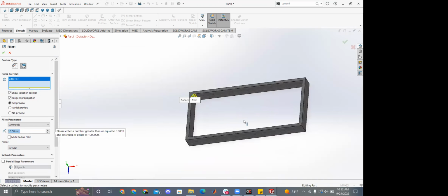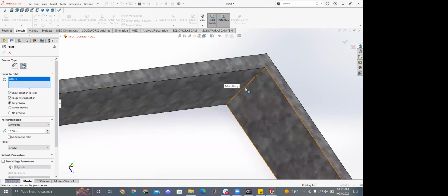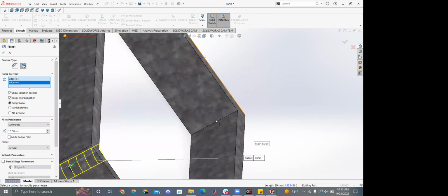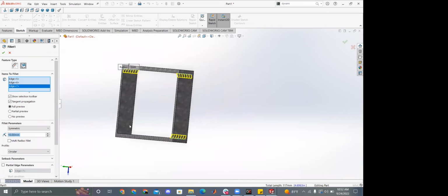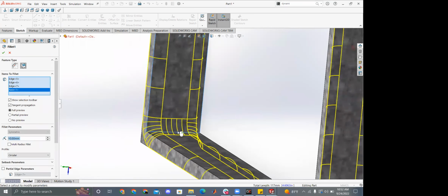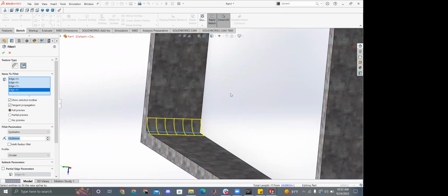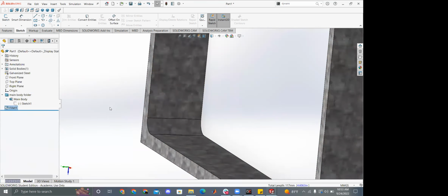So we want to make sure when we're changing things that are older in the body that we don't make too many changes that wholly delete and add new things, because that will create these kinds of errors. Doing this might not be so bad, but doing it for every single sketch or every single feature that follows an early feature and relates to a face or an edge or a corner in one of your old models is going to take you a long time. You have to go through each feature and change what's wrong. If you do it in the wrong order, of course, if you fix ones at the end before you fix ones at the beginning, you may change more things that things in the future are dependent on. That acts as a good segue into